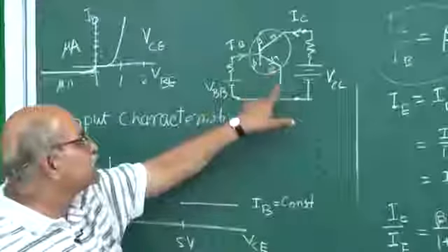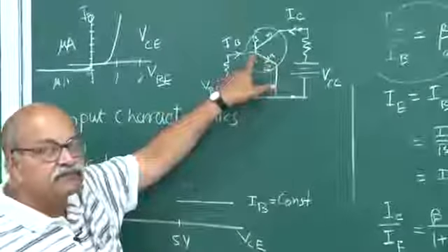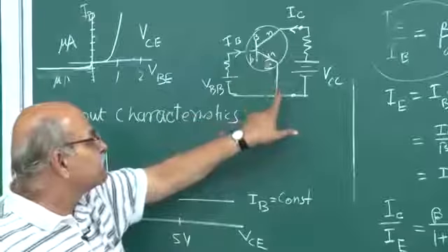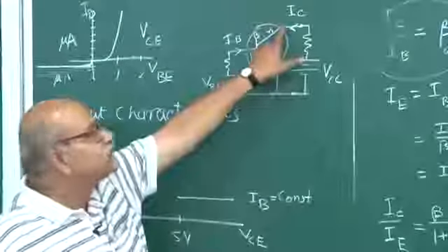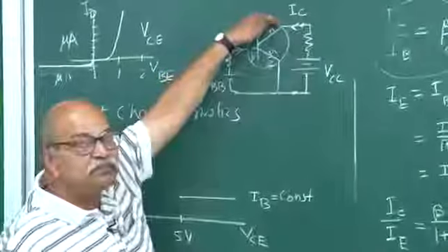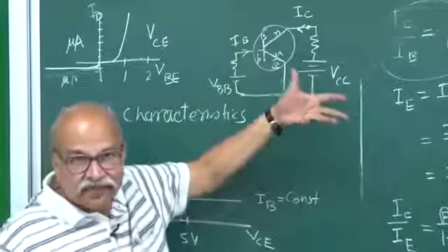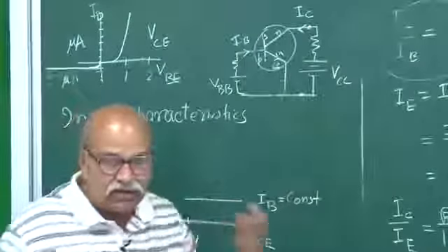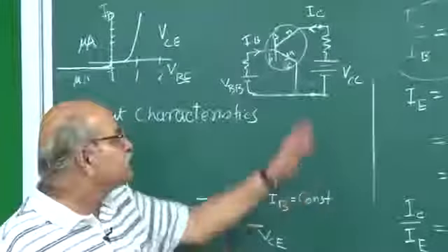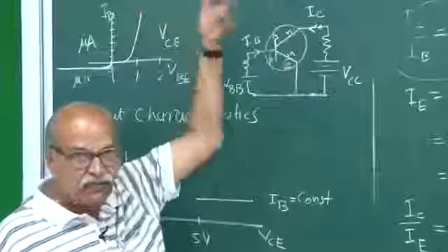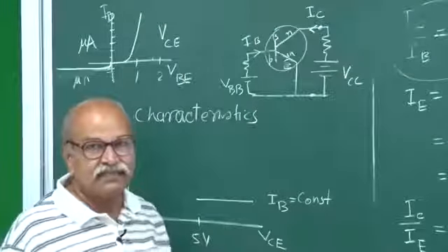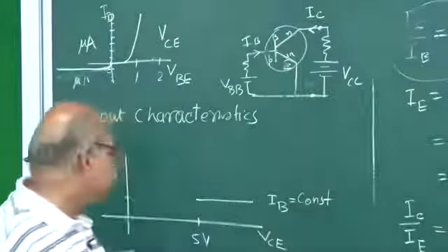So with respect to the base, this is also positive. So you don't have reverse bias, you have in fact forward bias, and it will not draw electrons from there, and these are lightly doped, they themselves are not going to give significant current. So this will be almost 0 here.